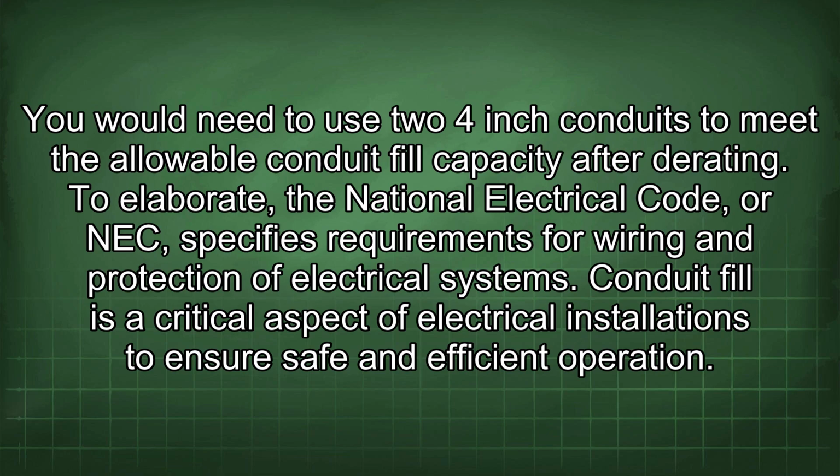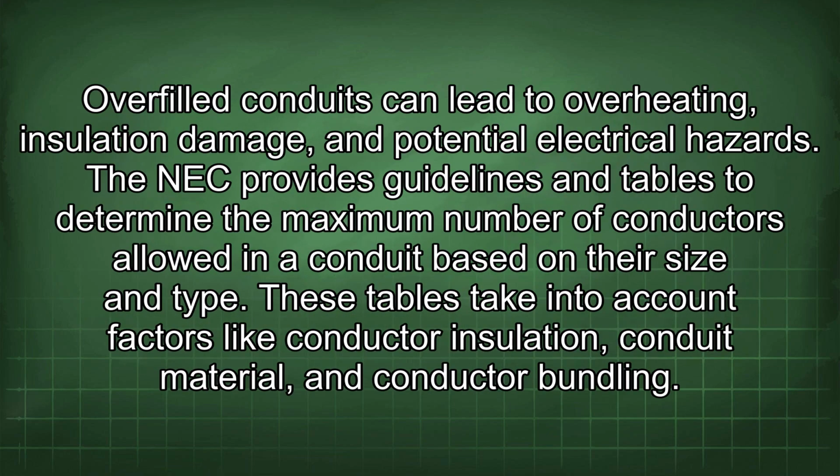To elaborate, the National Electrical Code, or NEC, specifies requirements for wiring and protection of electrical systems. Conduit fill is a critical aspect of electrical installations to ensure safe and efficient operation. Overfilled conduits can lead to overheating, insulation damage, and potential electrical hazards. The NEC provides guidelines and tables to determine the maximum number of conductors allowed in a conduit based on their size and type. These tables take into account factors like conductor insulation, conduit material, and conductor bundling.